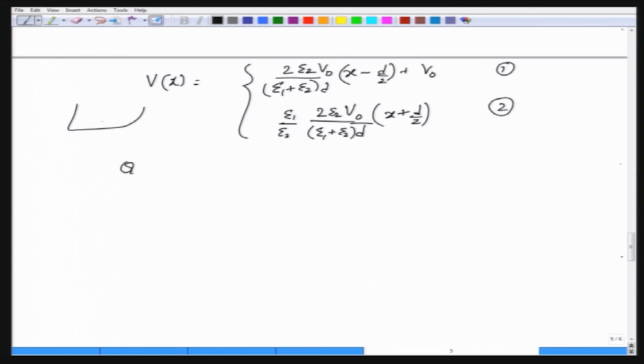So, if I have a top plate here, let me pick out a uniform surface element A and I want to find out what is the charge stored in this region. Okay, and if I find that, I can actually find out the capacitance, because capacitance is the charge on one plate divided by the potential difference between the two. The charge stored is of course the charge density times the surface area. I have already found out the charge density, right.